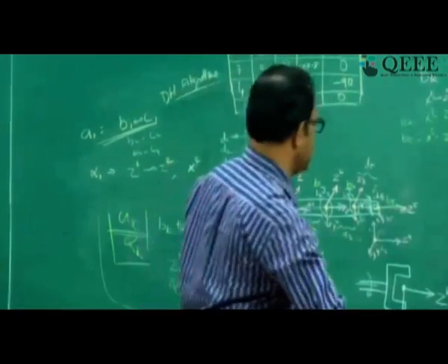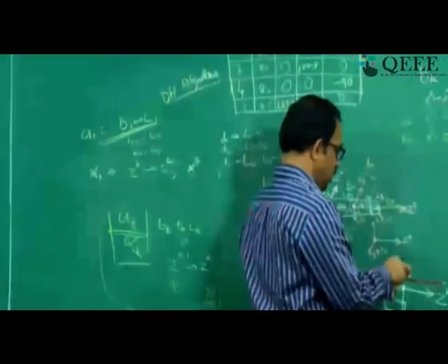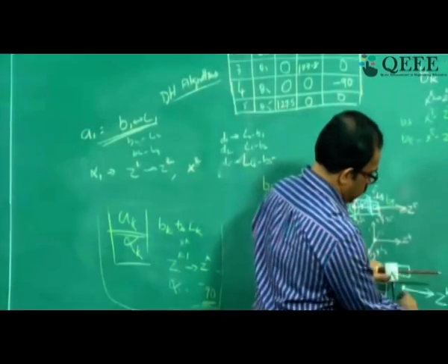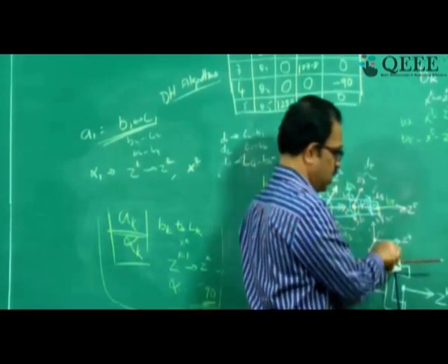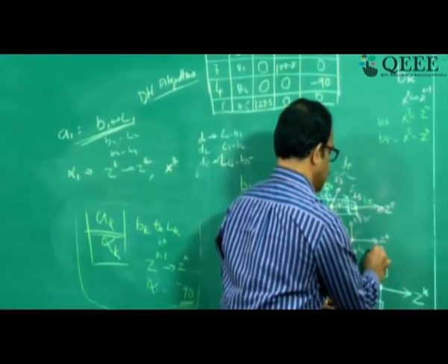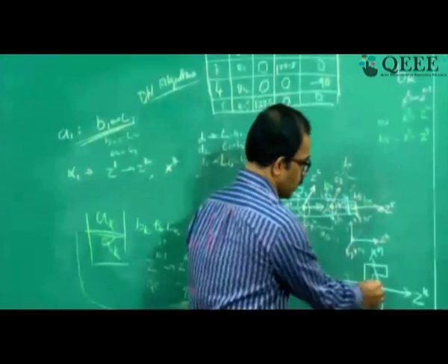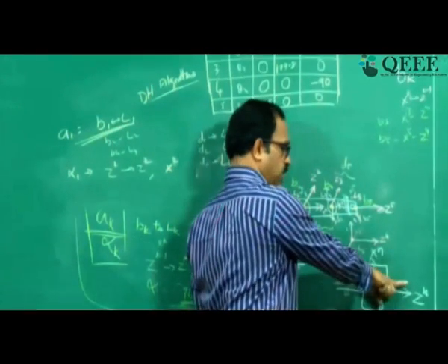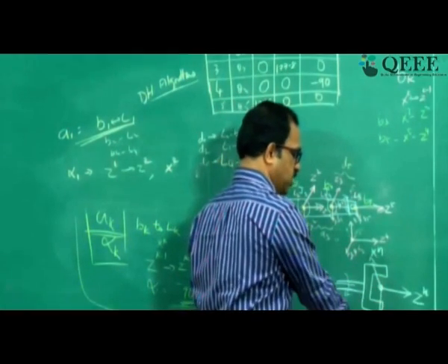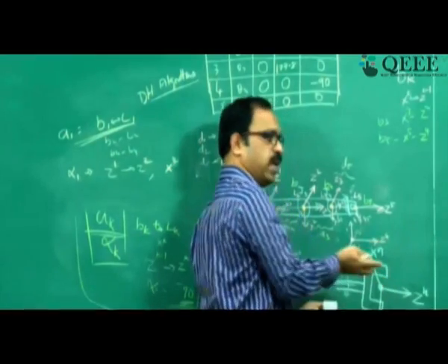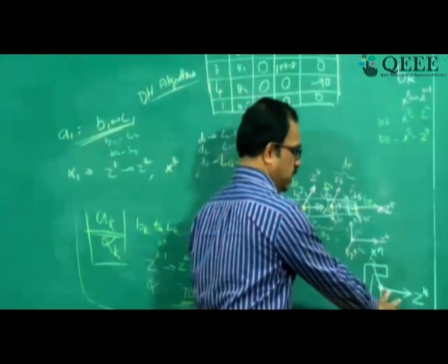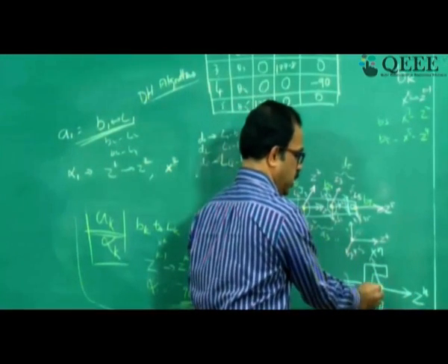So now if you look at this, this is your Z axis and this is the Y axis. So Z is in this direction, Y is in this direction, so X will be projecting out. So it will be like this, projecting out X N. So we call it as along the roll you have the Z axis, along the open close you have the pitch axis, and the X will be the yaw axis. So yaw, pitch and roll will be the way you assign the coordinate frame for the last tip or the tool tip.